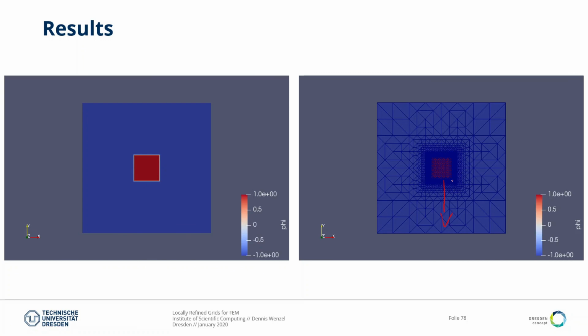So if I'm refining some cell here, it always affects my neighbors, so I can't just do hard cutting of the step size, but that's usually completely fine because it's very rare that you need a super fine grid right here, and one step further you can live with cells of this size. That's usually not the case. So recursivity naturally causes this slow decay of grid size, but that's completely fine in most cases.